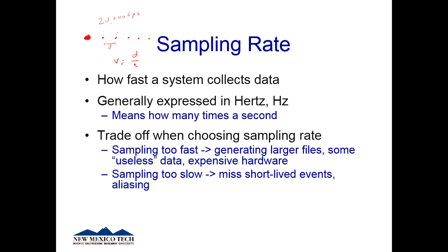Things like if you use a thermocouple for taking a temperature measurement. We'll talk about thermocouples in a couple weeks, but know that there's a wire, actually 2 wires, they're connected at a point, and we know that this point has to heat up. Now, if you put that inside of a housing, the housing has to heat up before the thermocouple can heat up. So we know that there's going to be a time delay there. So maybe we can only sample, I typically don't sample thermocouples much faster than 4 hertz because there's just no way the temperature changes faster than that.